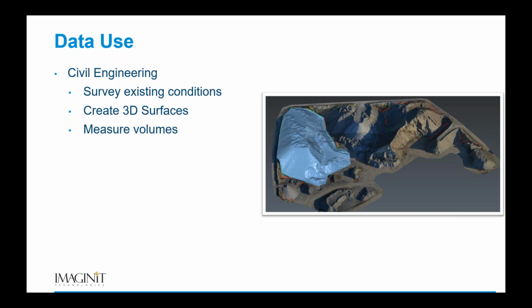What you're looking at here is a software created by Leica called Cyclone 3DR. It has a great stockpile feature where I can very easily draw a line around the outside of my pile and save that line for later. As that pile diminishes, I can keep calculating volumes to get differences. Okay? So, things to keep in mind.